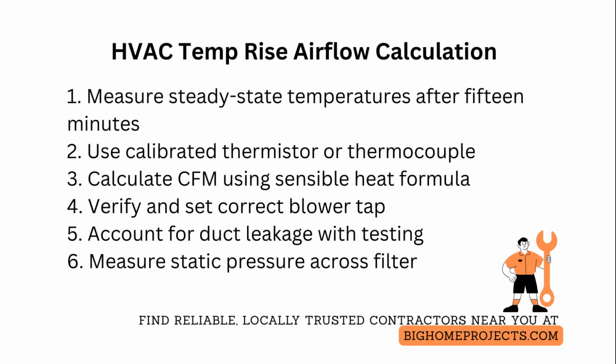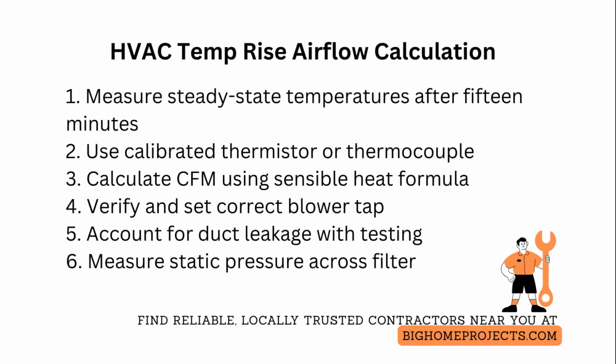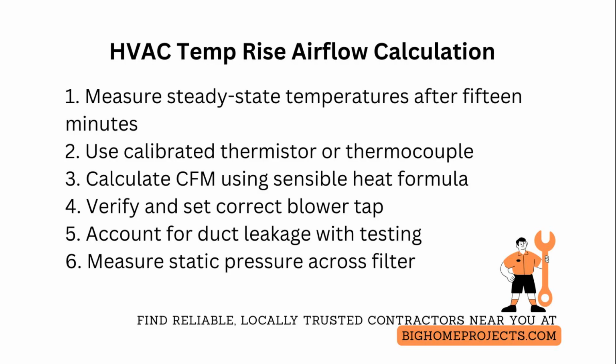For multi-speed motors with electronically commutated motors, use the motor control board settings and observe the fan command signal rather than assuming tap markings correspond to discrete speeds. Consult the motor datasheet for torque versus speed curves to refine CFM estimates. Always repeat measurements 2 more times under the same operational mode and average results to reduce transient error.